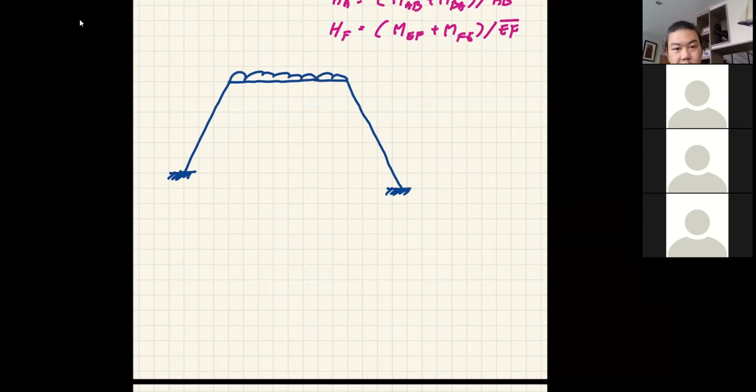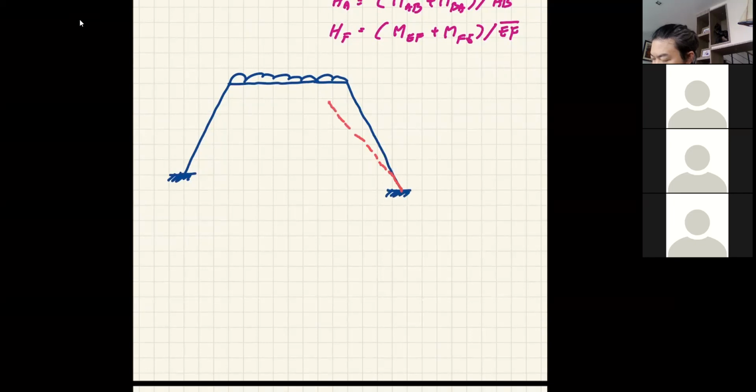Now you look at this member. It's not symmetric. It doesn't have any lateral load, but it will have side sway because it's not symmetric, because of the unequal legs like this. It's just going to go to the side like that. That means you probably see that this is a fixed support, right? So with zero rotations, but this guy could just go down like this. See? And that becomes your psi term. If I should connect these, that becomes my psi term,